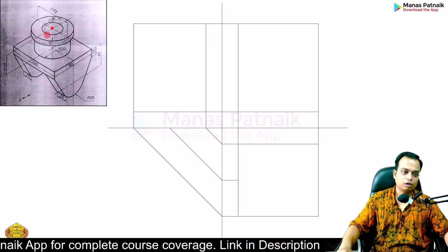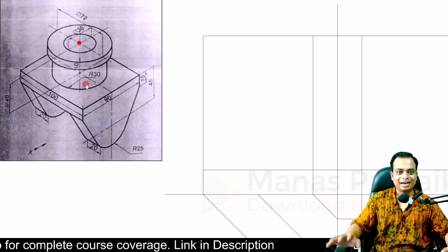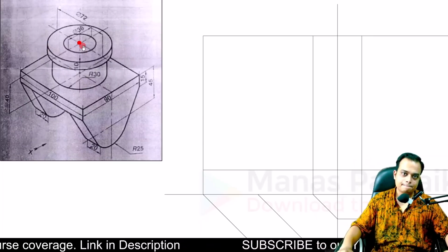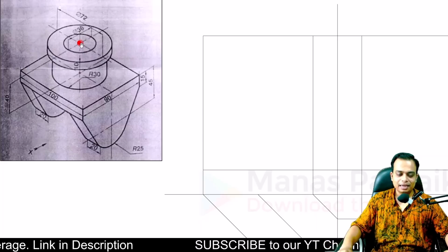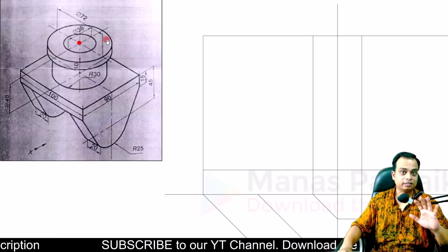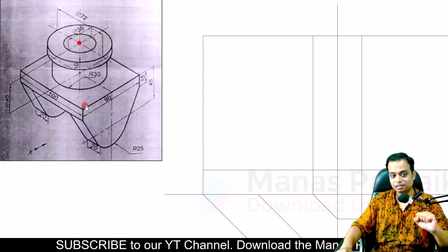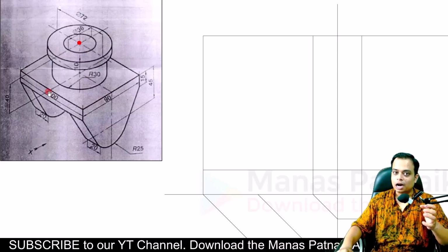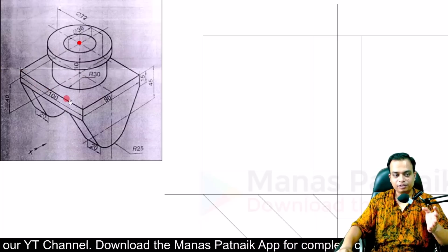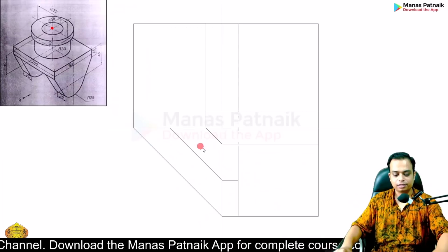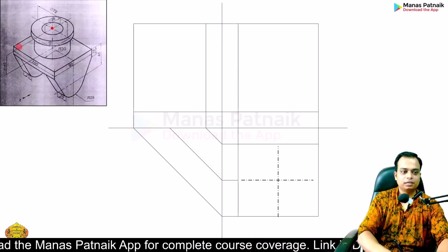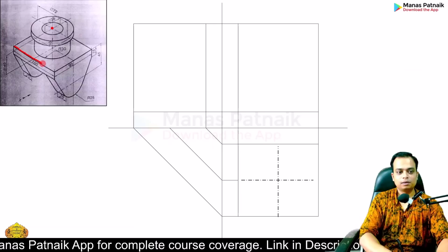Okay, having worked out the dimensions of all the boxes, now we shall go ahead and find this center's location. If you watch, right now we are interested in creating the top view. In the top, you are going to see this center. This center is a center for the circles. There are going to be 3 concentric circles, let me tell you, as well as the center for the rectangle also. So half the dimensions 50, and this is 45. Half of 100, 50, half of 90, 45. Here we go. Done. Okay. Secondly, if you watch, this is what you will see from the top, this edge.